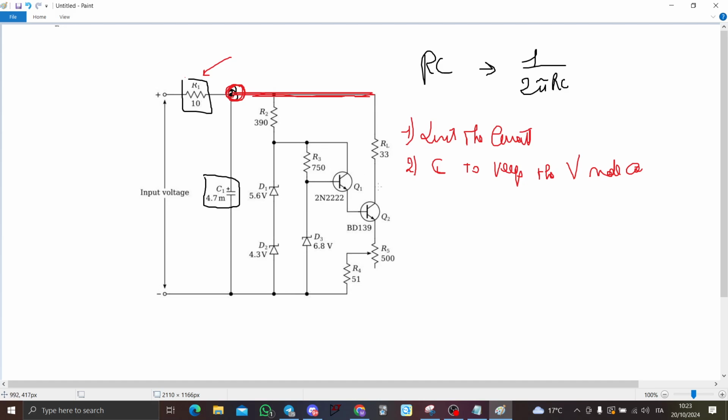and if there are any pulsed load, any load variation, this capacitor will provide energy first, and so you will have a voltage as constant as possible, because this capacitor here, so this is the voltage V, this capacitor here will provide a burst of current I, because it is a very, very big capacitor.